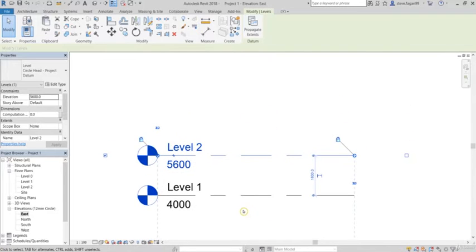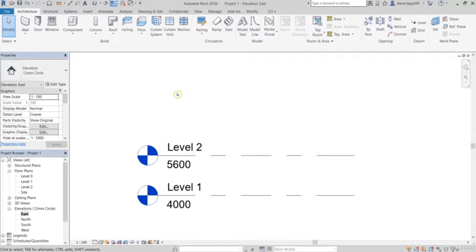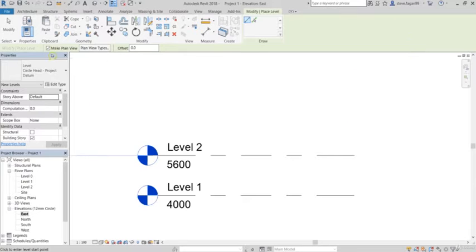Okay, so I'm going to pan up again. So I'm going to go into a bit more detail of placing the level. So again, pressing escape to come back to the main model, clicking on my level tool, and in here I'll go over my options. So the very first one there is make plan view, and that's turned on right now. So when I place my level 2 here, if you come over to the project browser, under the floor plans, we have level 0, level 1, and now we have level 2.